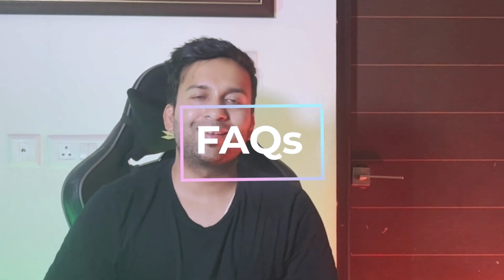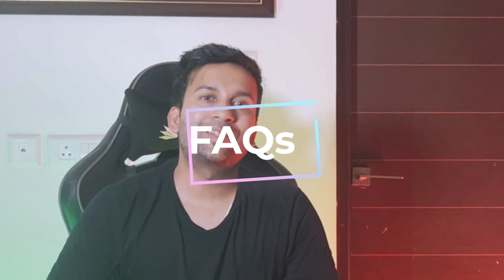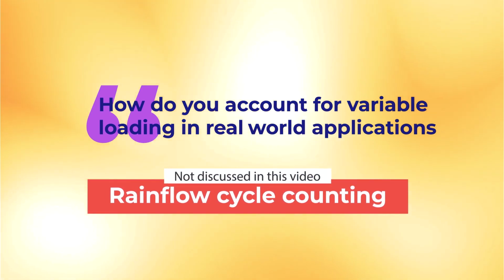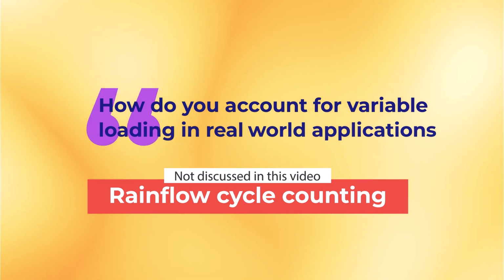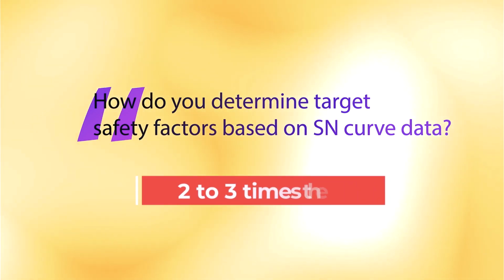Before we wrap up, let's look at some common questions that users may encounter. For example, engineers wonder what the best methods are to account for variable amplitude loading in fatigue analysis. Techniques like rainflow cycle counting and linear damage accumulation models like Miner's rule provide good estimations, but more sophisticated computational methods continue to emerge. On the practical side, those working on product development often ask how to determine target safety factors when designing new components.